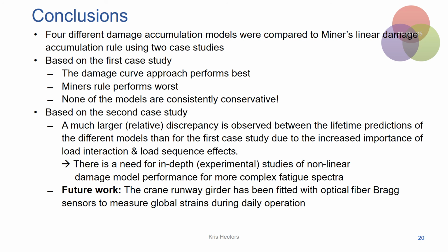Finally, I want to finish by saying that we have fitted the crane runway girder in this study with optical fiber Bragg sensors to measure the strains during daily operations. This in the future will allow us to experimentally validate the finite element model shown in this presentation and to perform a more extended study with actual load data.